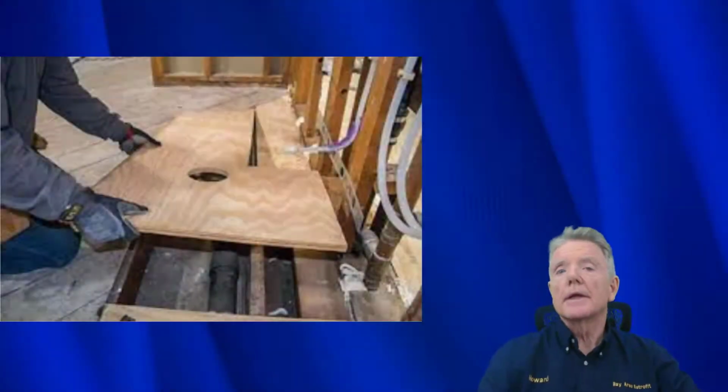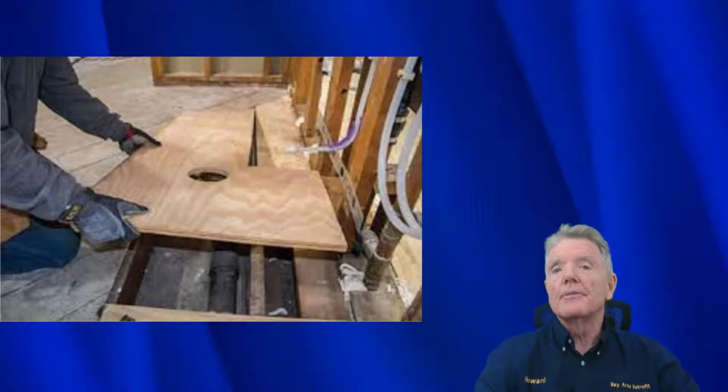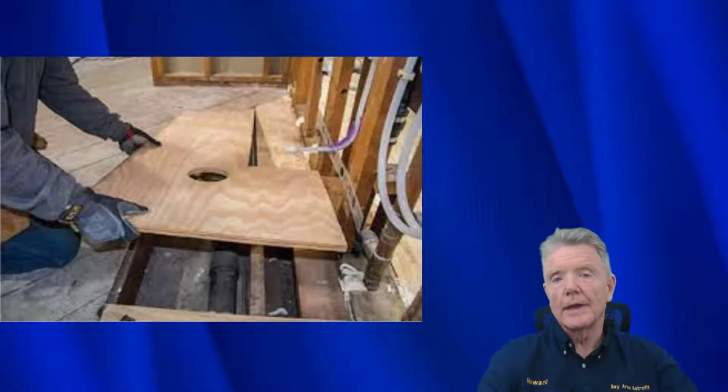So right now we're going to be looking at the problems that can arise when people repair their floors. What happens is there'll be dry rot, there'll be a kitchen remodel, whatever it is. There's some reason they'll replace the floor with plywood. So there's the old floor that's made out of oak and Douglas fir planks or whatever it is. They tear part of that up and they replace it with plywood. And that can be a problem because it can interfere with the transfer of earthquake forces through the floor into the foundation, and we're going to go look and see how that's repaired right now.